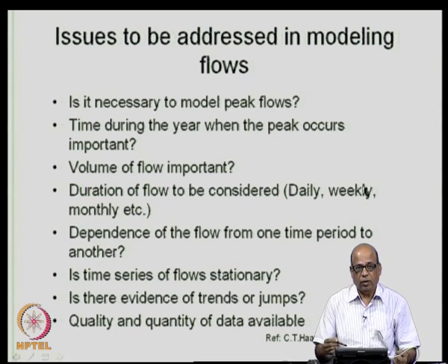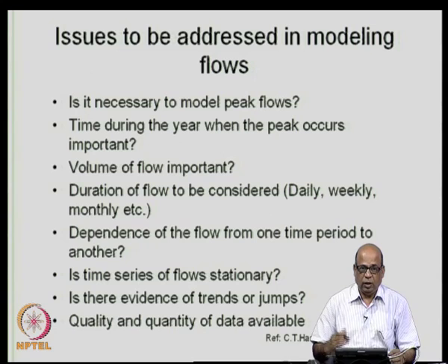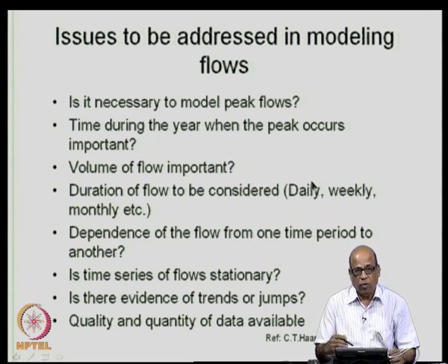As it is fairly obvious, depending on the duration of the flow that you want to consider, the type of the model that you would like to fit can be quite different. From annual to season to about months, you can still use the first order Markov model, either the stationary version or the non-stationary version of it. But as you start reducing your time periods, let us say you come down to weekly time period, daily time period and so on, then the assumption of normality of flows will be violated, and therefore, you may not be able to use such models. Then you will have to go for different type of models, which we will subsequently discuss in this course.